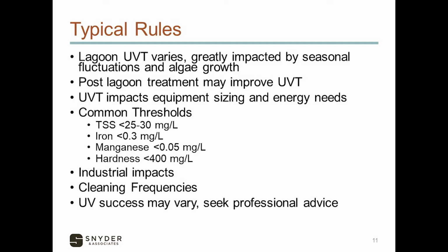Color can affect UVT. Oftentimes, some colors have a greater effect than others. Use of chemicals upstream, like ferric chloride, can affect UVT. Many of you may have industries that apply ferric chloride to their process. Some of you may even use ferric chloride in your own process. So that one's a big one. And remember, it's the iron that's the big deal. All tubes will need to be cleaned. It's just a matter of how often. More frequently cleaning the tubes may be required in warmer months, or if you live in a warmer climate because you have a lot more algae growth.